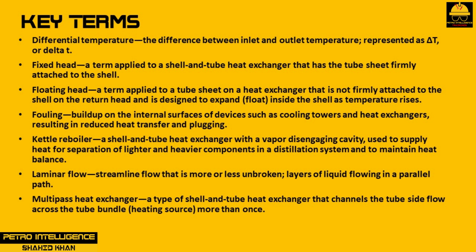temperature rises. Fouling is buildup on the internal surfaces of devices such as cooling towers and heat exchangers, resulting in reduced heat transfer and plugging. Kettle reboiler is a shell and tube heat exchanger with a vapor disengaging cavity, used to supply heat for separation of lighter and heavier components in a distillation system and to maintain heat balance.